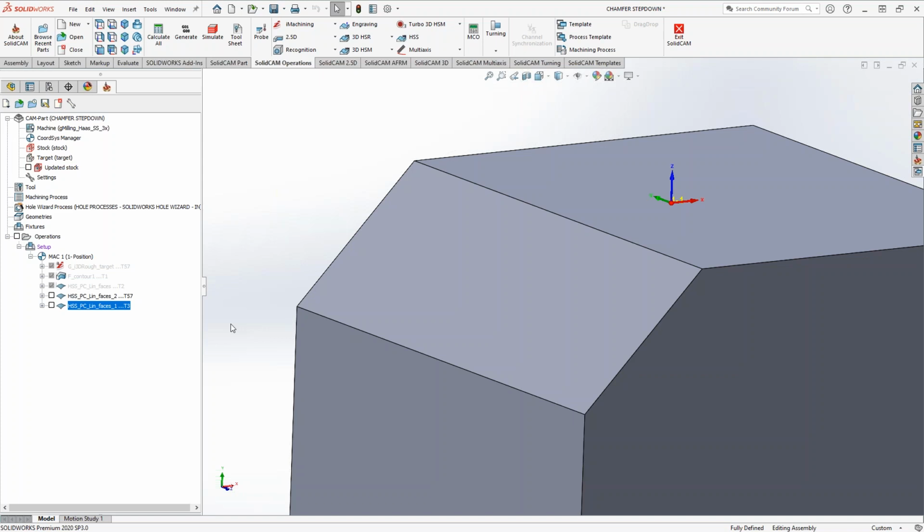So if you look at the geometry of your scallop, it's literally just two arcs, right? So there's the height there, and that would be Z. What Brian is saying is RZ is the max valley to peak. So yes, Brian, you're 100%. That is the max that it is set up, where RA is the average. And when you measure it, I don't remember what the machine is called, but you stick the little machine on there and it takes a sweep over a bunch of scallops, not just one. So to Brian's point, yes, exactly. It's taking the average of all of them.